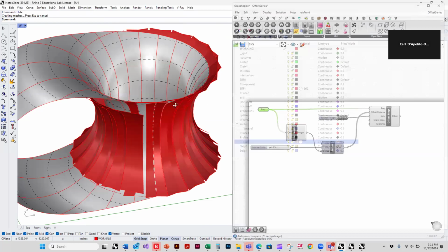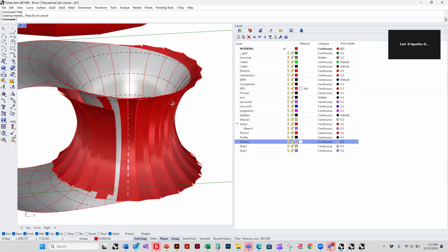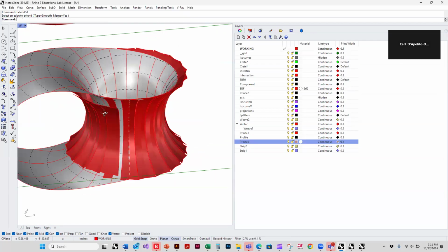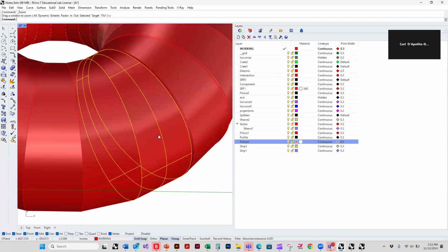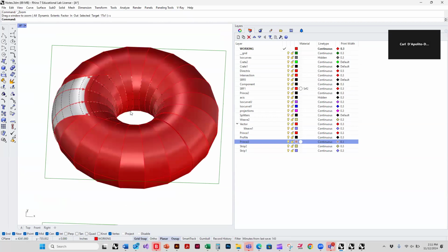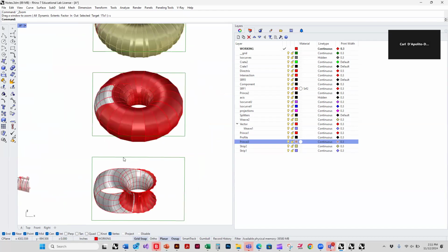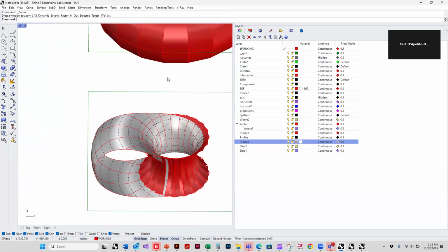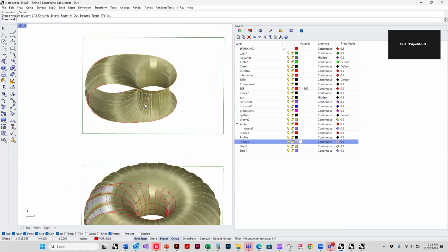you'll see that by the time it gets around offsetting, I extended these too much, so the overlap is too much. The thickness is built up. Let me show you the one I made previously. I made one with a full torus, and the reason is it's easier, I think, to trim the strips than to construct each strip individually. And then I array them around like this.